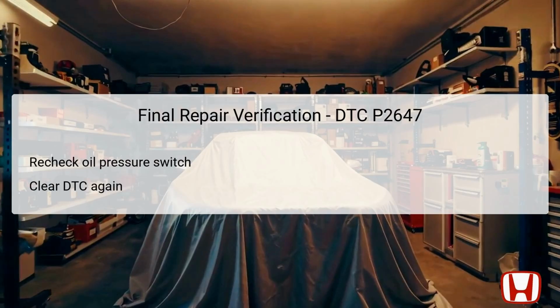Start by rechecking the rocker arm oil pressure switch to ensure it is fully operational and free from defects. Then make sure all electrical connections have been restored correctly and securely attached. Following this, use the Honda Diagnostic System, HDS, to clear any remaining DTCs. Once cleared, conduct another VTEC test from the inspection menu to confirm that the system functions correctly without triggering any errors. This stage is critical because it verifies that the repairs have effectively resolved the initial issue, ensuring that the vehicle operates as intended without further complications.